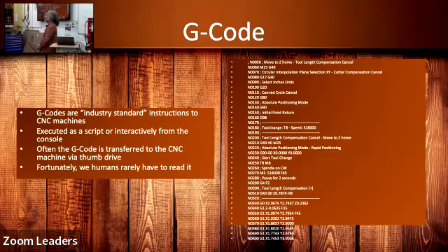It just tells you, for example, right here, it says go to X equals 1.8657, where it was before, it was 1.9302. So the X-axis, the bit is going to travel from 1.9302 to 1.8657, while the Y is moving from 2.8475 to 2.9. So in other words, it doesn't have to be right angles. It travels point to point. Right. And this just tells you from this point to this point, from this point to this point. Depending upon what shape you're trying to do, it makes a very nice circle, for example, by making a whole bunch of little steps.